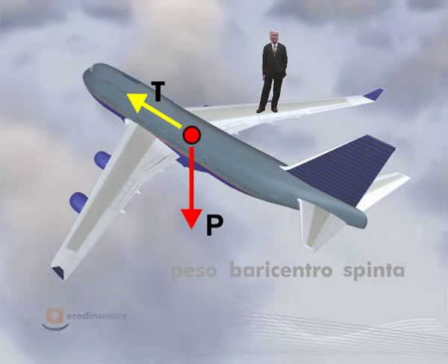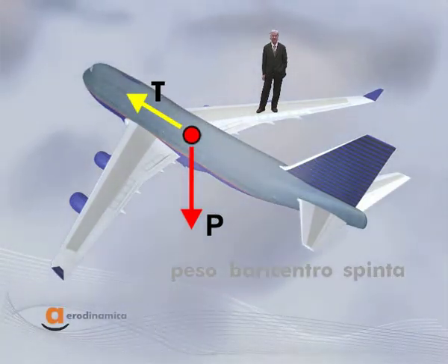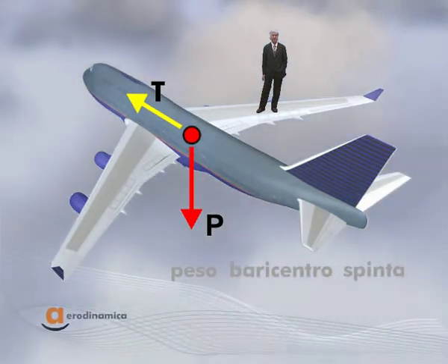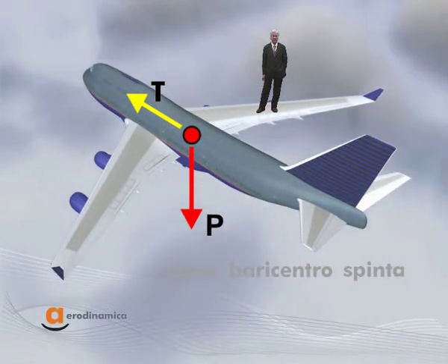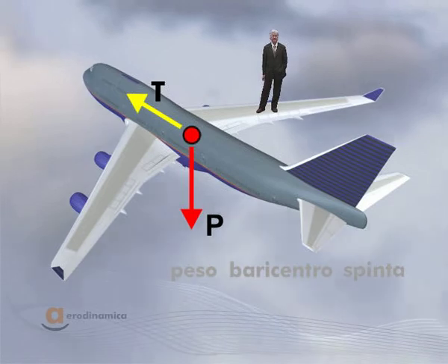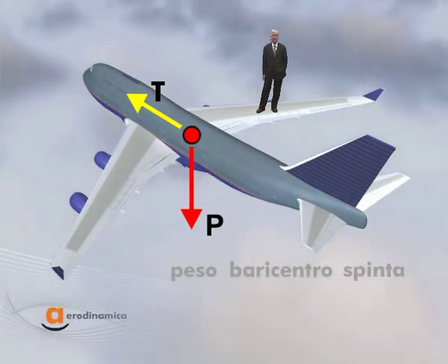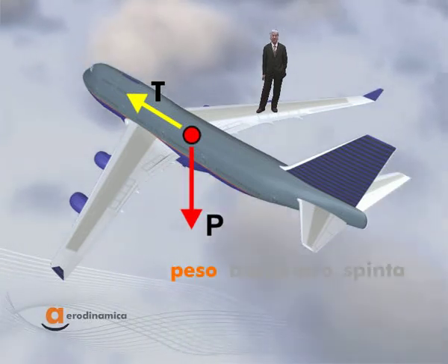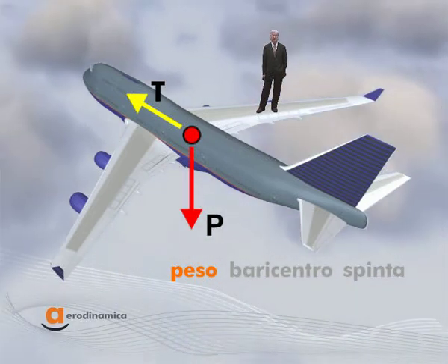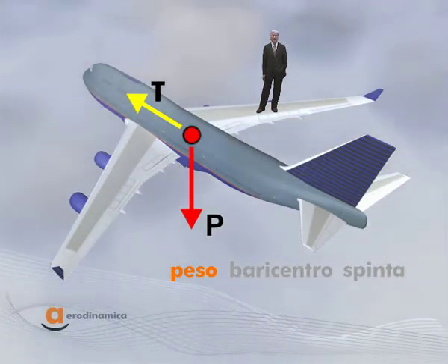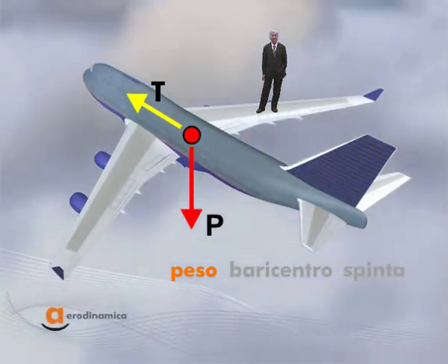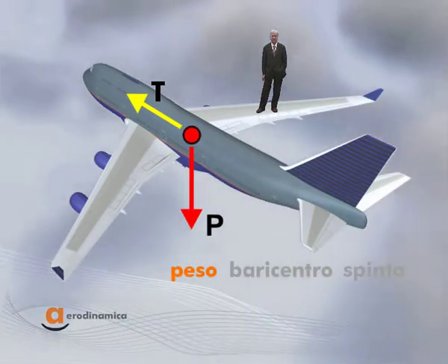On a general airplane like our P-68, the variations are very small. Yet, on a B-747, they may be relevant. Taking into consideration the weight variations at a constant speed and altitude, the pilot has to lower the altitude to obtain the necessary lift coefficient.